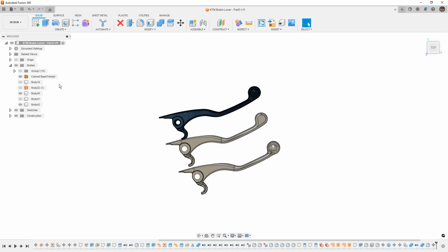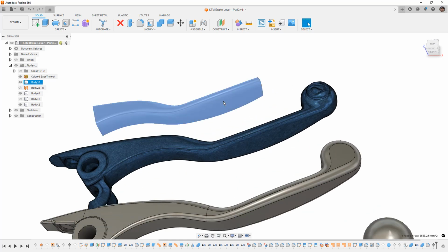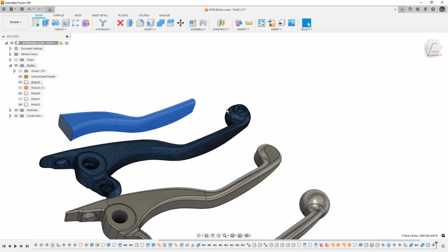So when we first started this project, we were looking at using mesh section sketches. The mesh section sketches were a great way to capture the exact detail of the mesh, but the limitation is that the actual splines that we got were really noisy. So there's not a great way to smooth or average those out and still maintain that level of detail that we have in the scan. You could do those manually and get pretty close, but using those automated tools, unless we're using the mesh section sketches for a line or an arc or a circle, when we get into those splines, it just gets really messy.